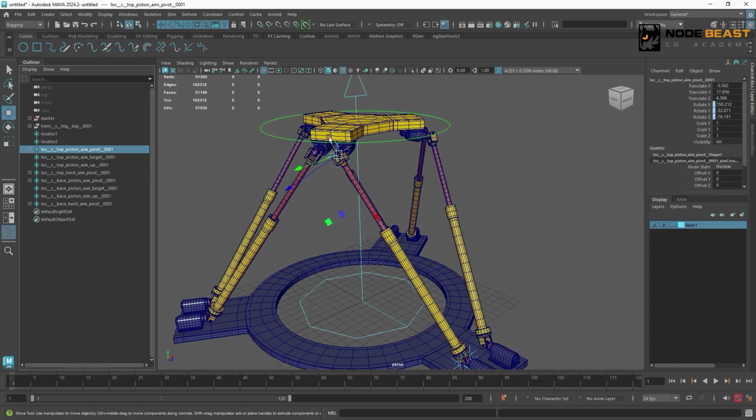But right now, that's clearly not possible, because these locators need to point to these corresponding positions. So what can we do? We know translate, rotate, and scale. Their values are relative to their parent's coordinate system. Right now, their reference coordinate system is the world, because they don't have any parent object. But if we add a parent object, and this parent object has the same rotation as it currently does, couldn't we zero out its rotation values?